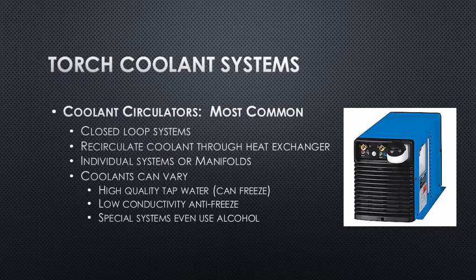Coolants can vary. They range from high quality tap water, which can freeze in some applications, so that's a concern. When that is a concern, you should use a low conductivity antifreeze from the manufacturer of the welding equipment. Do not use automotive antifreeze because that contains minerals that can conduct high frequency away from the arc, which can cause arc issues when you're welding. Some special systems even use alcohol, and that actually provides excellent cooling, but you have to have the right cooler and the right hardware designed to use that as a cooling system.